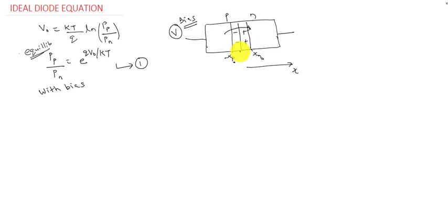If we apply reverse bias voltage, the depletion region width will increase, or we can say the position of xn and minus xp will change. With the applied bias, the value of minus xp and xn will change. It will move either right or left depending upon the biasing, which means the depletion region width is increasing or decreasing depending upon the bias condition.